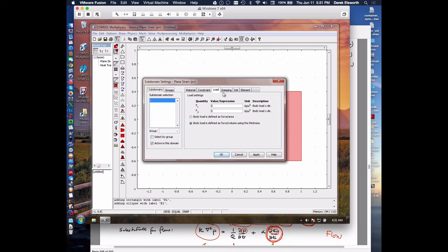And I suppose the other thing that we want to know is what the variables are that are used in this. And okay, so actually this is the part we couldn't see before. We talked about isoparametric elements and the order of integration. So this is using 4-point quadrature for the integration. And I'm not sure what the constraint order is, but it's using quite a high order. And so you can change those.